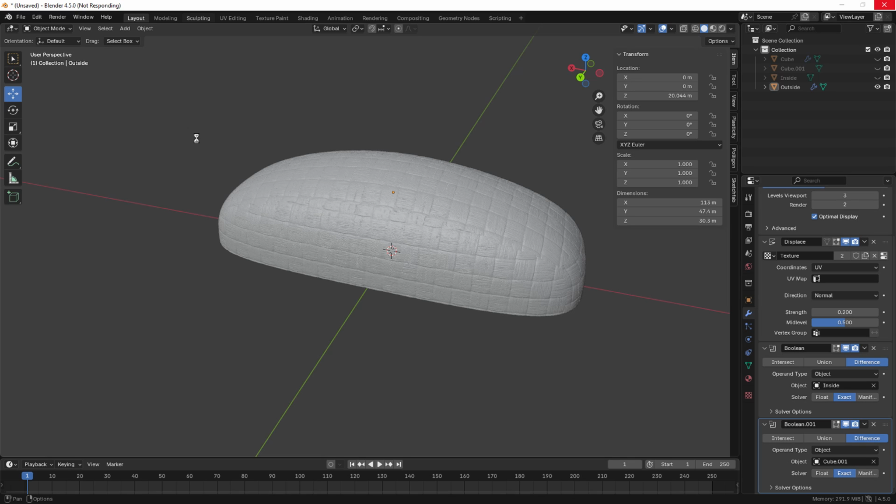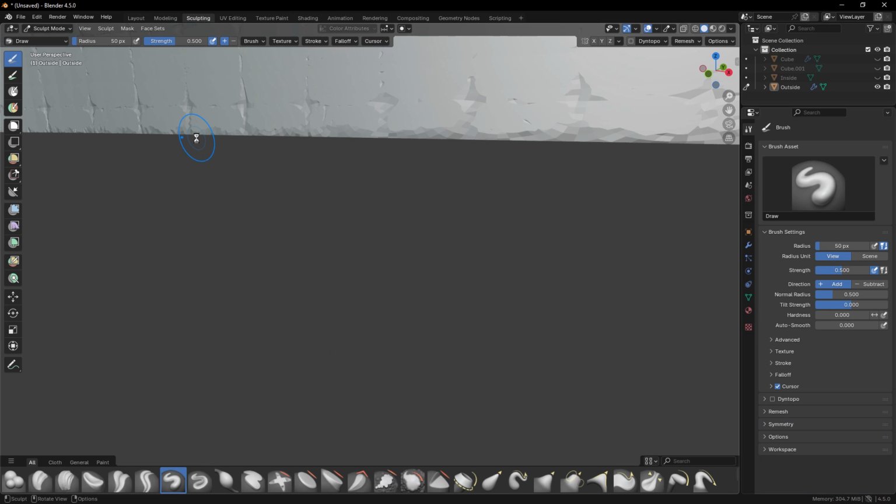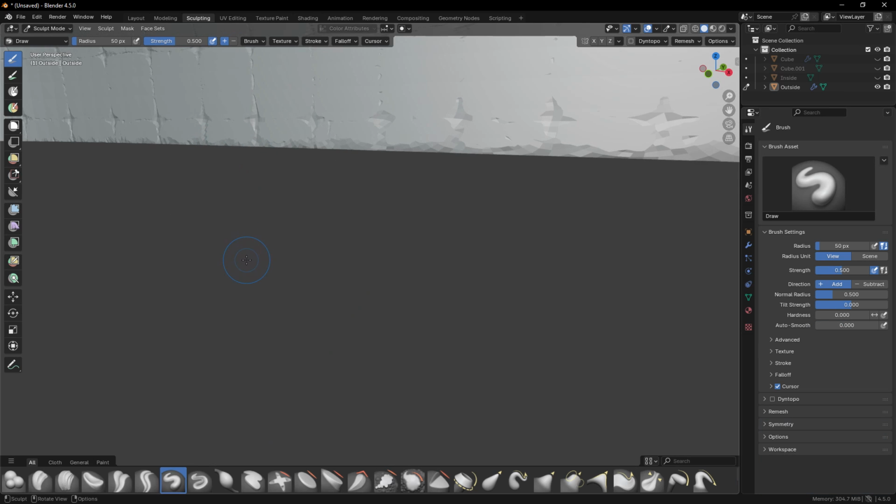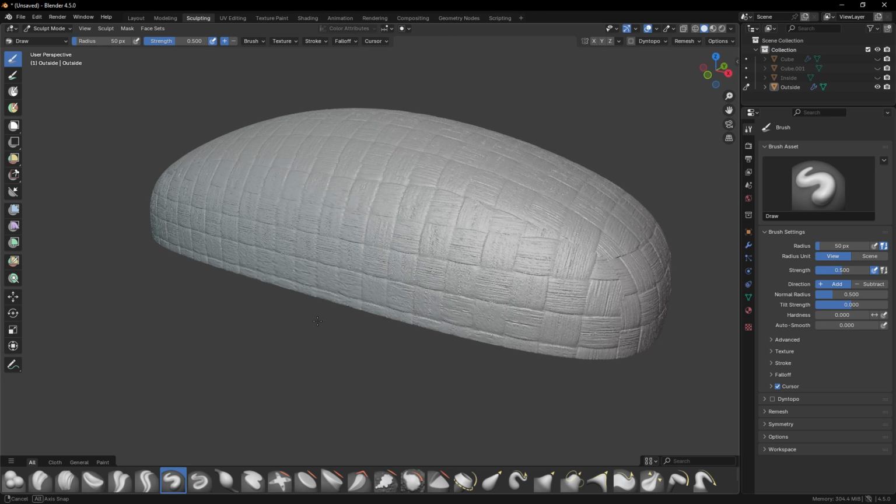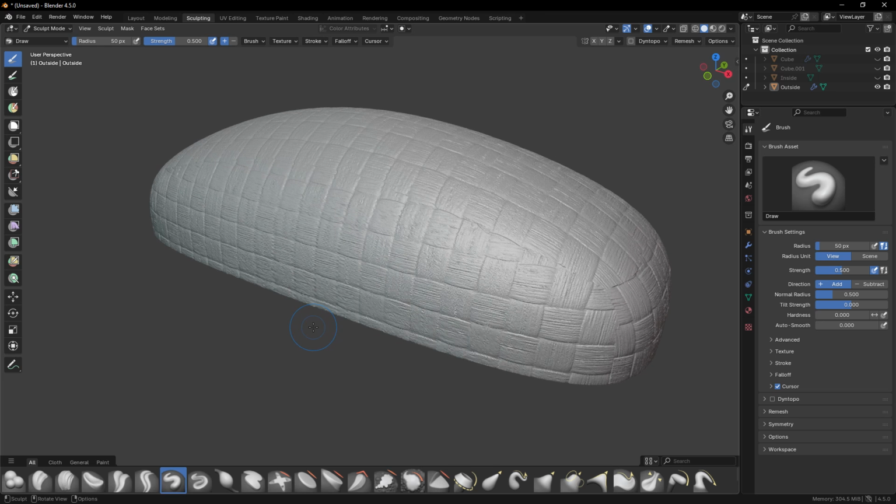Now, I did play around with this technique on the front fender that we created for the GPZ build series, which I do still have to get back to, just have kind of been on the bottom of my list. So I have tried this to do it on larger models. And again, the performance is not great when you have a CAD model that's converted. It definitely works a lot better and more efficiently if you create the model in Blender as a true quad model. But if you bring in a triangular mesh, just keep in mind that there is going to be a performance hangup.